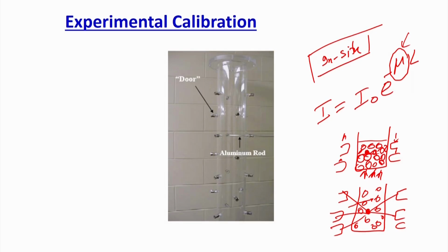So generally what we do in our lab, we put several ports near the wall. These are the ports, okay, and I know the ports because while designing the column I put the ports, I know the R, theta and Z position of these ports. Instead of R, theta and Z, if it's a rectangular column, I will say X, Y, Z position of the tracer particle. So I already know these ports.